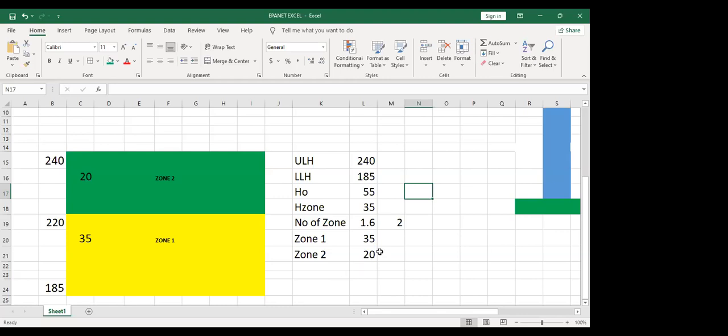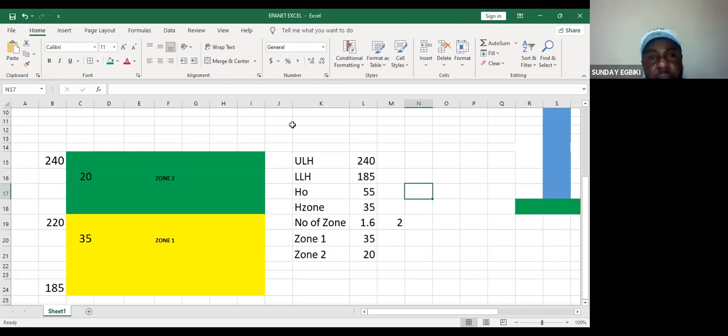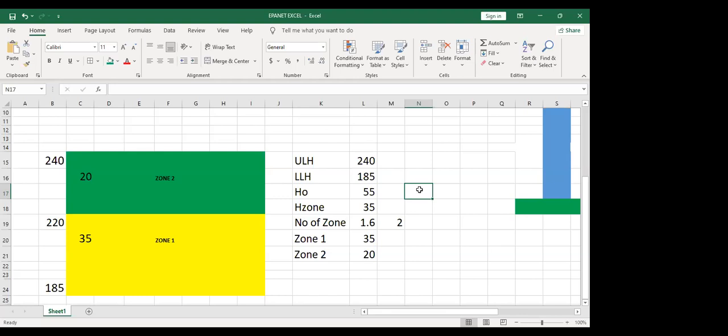Yes, sorry for hanging on this point with this Excel, but the height of the tower. First of all, when we talk of height, I guess we talk about the height at the outlet of the tank. Should the height of the outlet of the tower be 20 meters higher for one tower and for the other zone, meaning the outlet height of the tank should be at 260, respectively 240, isn't it?